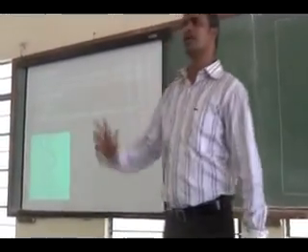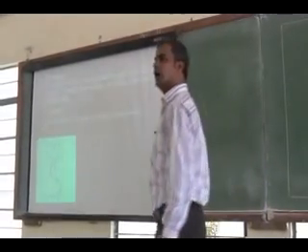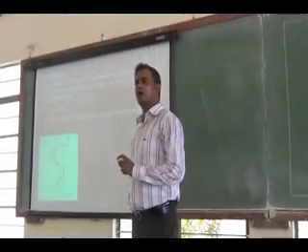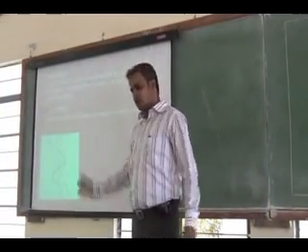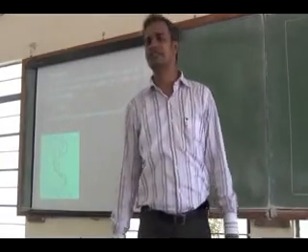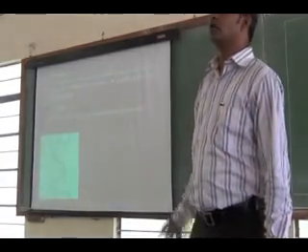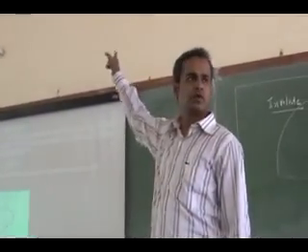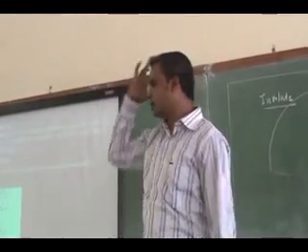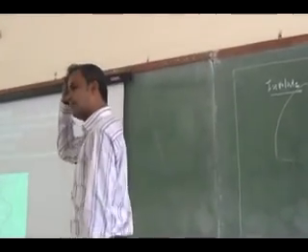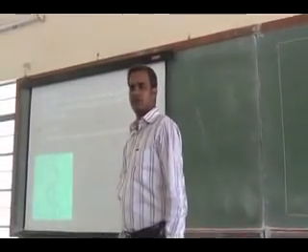To have a smooth velocity transmission and to avoid slip between the gears, there should be an involute profile or a cycloidal profile. Mostly in all gears, involute profiles are used. Cycloidal profiles are a little bit costlier in manufacturing.